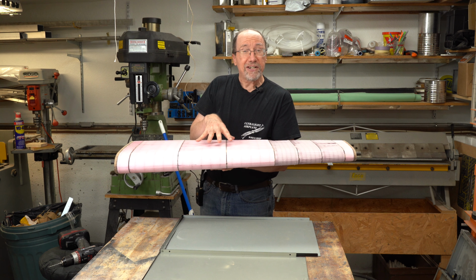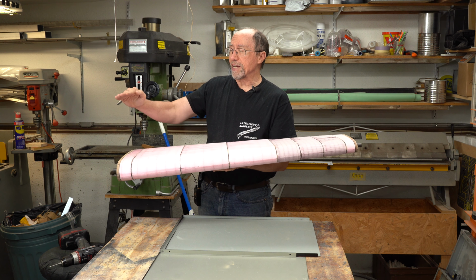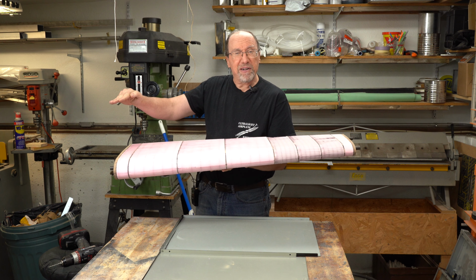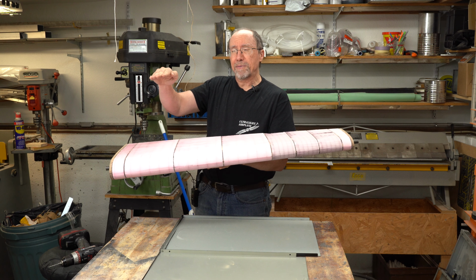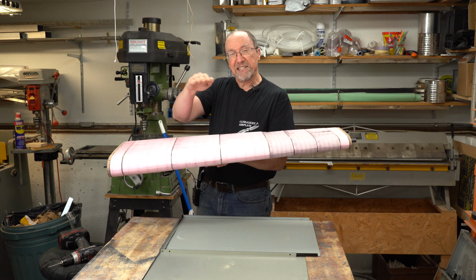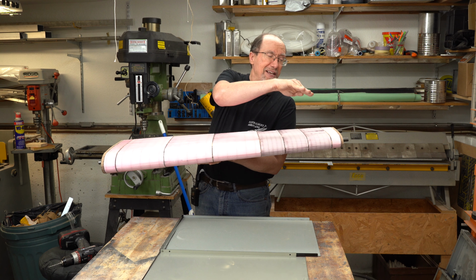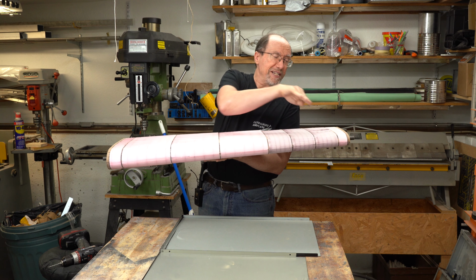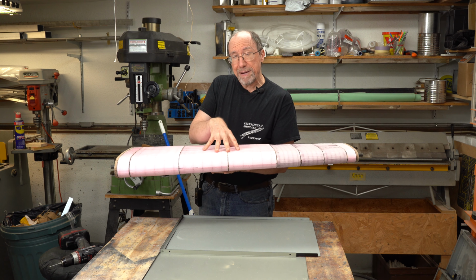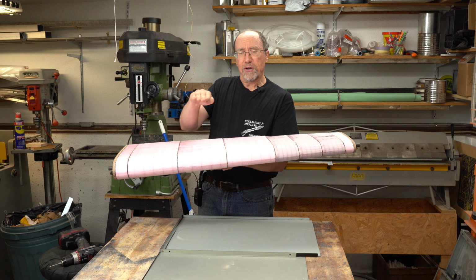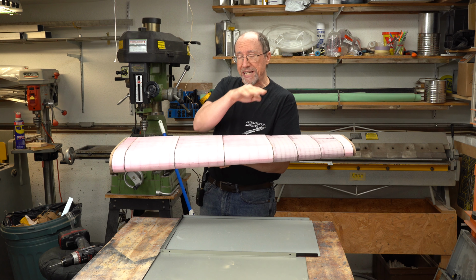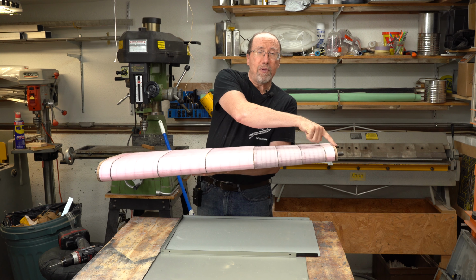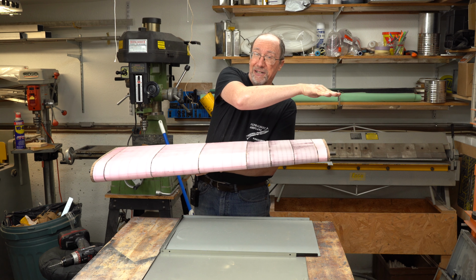On a tapered wing, you're actually going to get something a little bit different. On a tapered wing, it's going to start out at a certain spot fairly high, and then it's actually going to come up to a maximum up around this area, and then taper off, similar to the way a rectangular wing would taper off. The more taper you add to the wing, the farther out that maximum position gets. And if you actually bring it out to a sharp point, your maximum is actually out here at the tip.